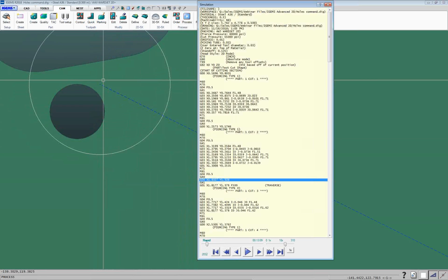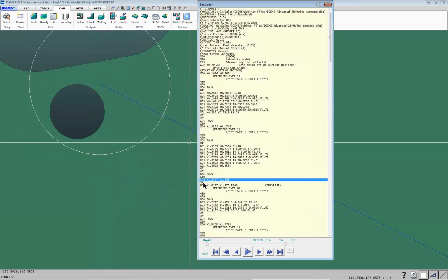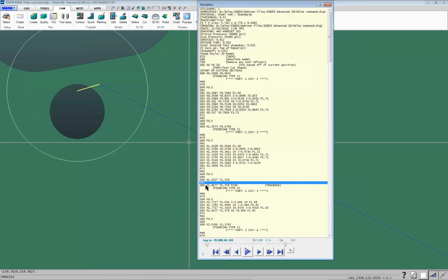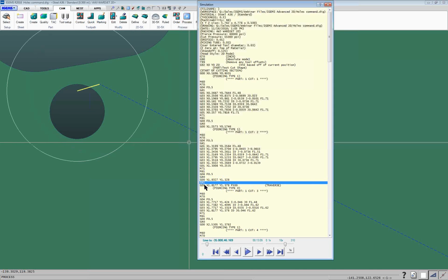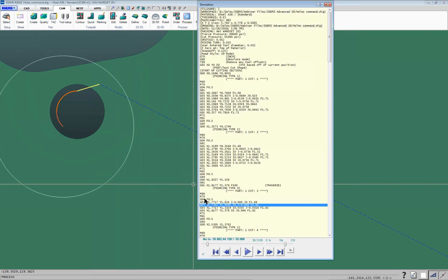And then in order to apply the tool offset, which is through the G41 move here, we do a rapid move with the tool off, but instead of doing that rapid move as a G00 like we normally do for a rapid move, we do it as a G01, which is a linear move with a feed rate applied to it. And then we can apply tool offset to that little rapid move, and then we come to the edge of the cut and then turn our water and abrasive on. So those are a couple different ways that you can add lead-ins if you have very small holes.